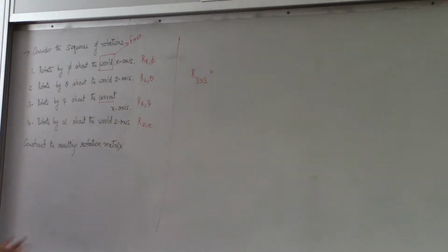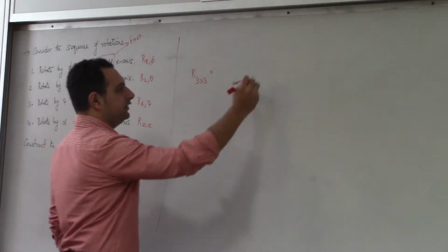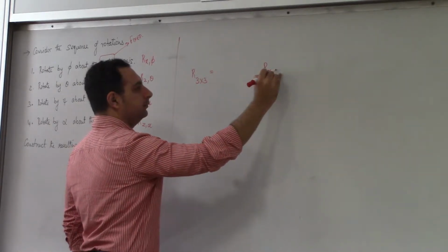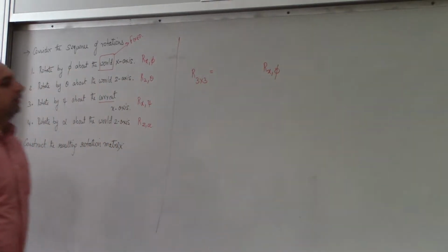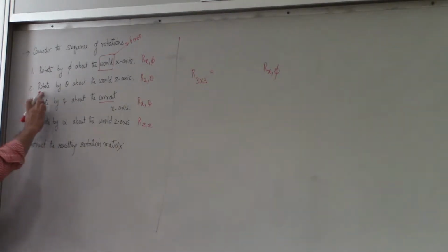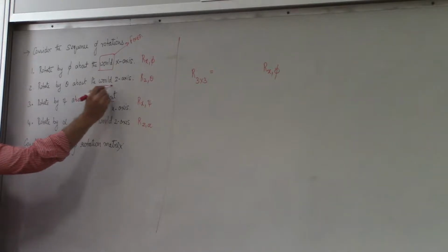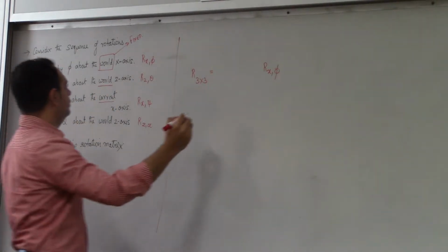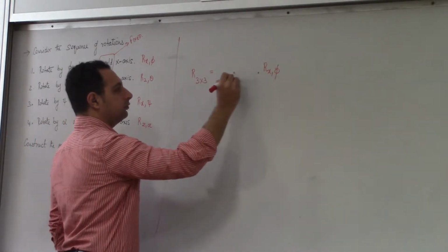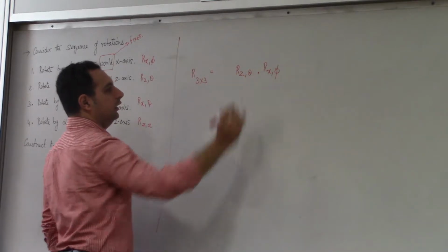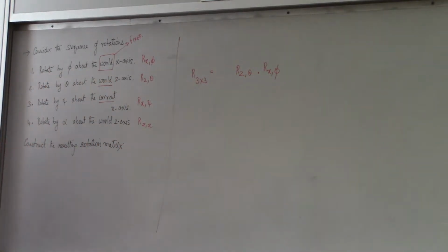The first rotation, obviously, makes no difference if it's a current or a fixed axis. So you'll write it as R, X, phi. Alright? This is your first rotation. The second rotation is about, again, a fixed axis. So this should be pre-multiplied because it's a fixed axis rotation. So we'll go here. R z theta. Okay? This is the second one.